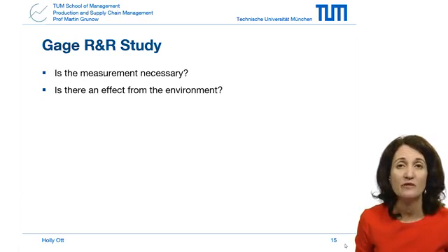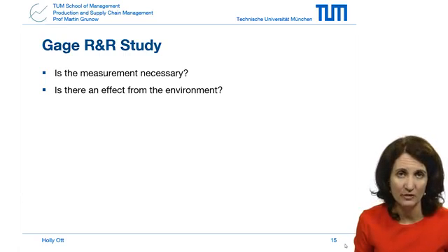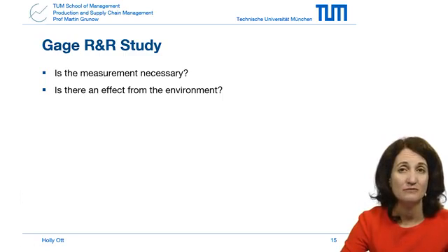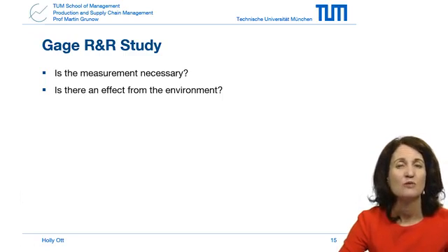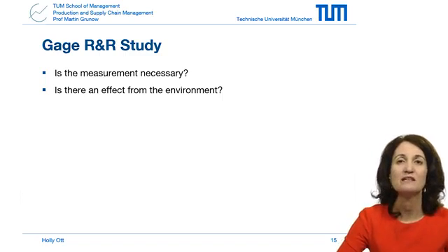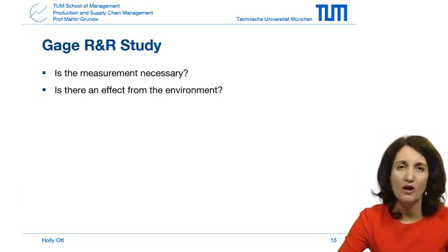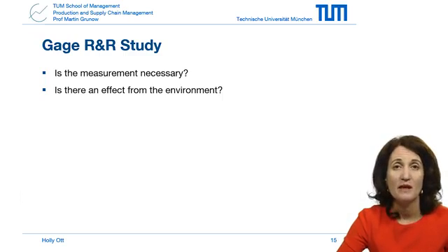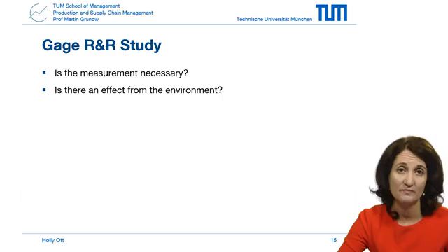Also, a preliminary evaluation should be made whether or not the instrument in question is affected by the environment in which the measurement is taken. This can be things like ambient temperature, often humidity or even lighting that could affect the measurement, as well as, for example, maybe you have some kind of accumulation of gas or something else. These are some of the factors that often affect the measuring process without people realizing. If any such factors seem to influence the measurement, then there need to be further experiments to evaluate the instrument, taking these factors into consideration.